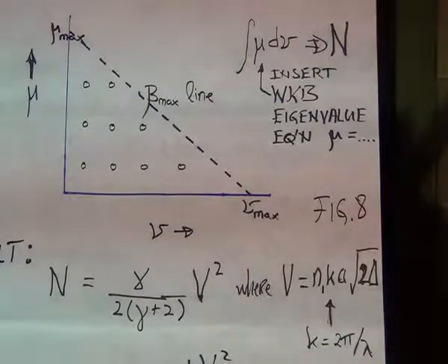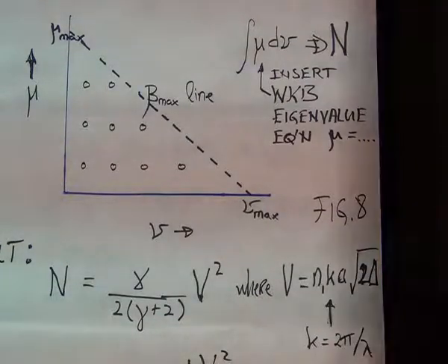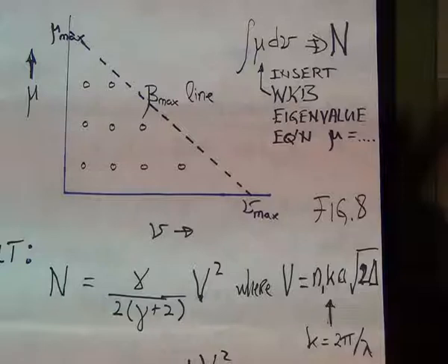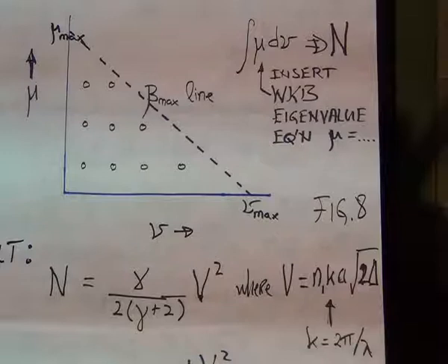Turns out you're close to the number of modes. You have to actually multiply that number by 2, because when you started with the wave equation, you said cosine of nu phi. You could equally have said sine of nu phi, and you get an equally valid set of solutions to the wave equation.